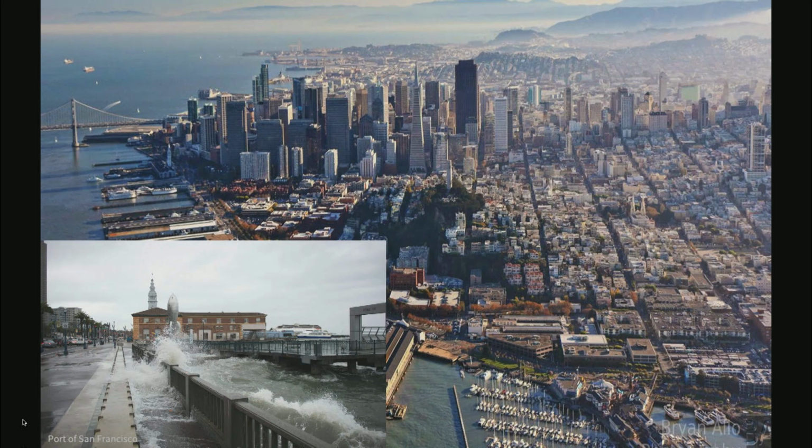Additionally, many of you probably know that the waterfront of San Francisco is not the natural waterfront that was there hundreds of years ago. During the gold rush, there was a lot of fill dumped in along the shoreline to create additional land. That material is not very well compacted, and during earthquake shaking, it's very susceptible to settlement and lateral spreading. This is that same waterfront area.